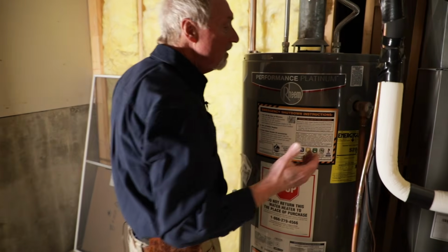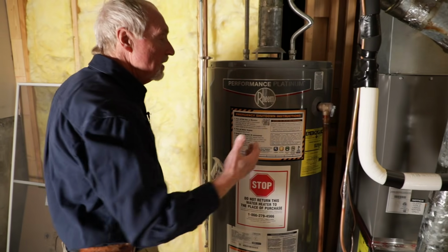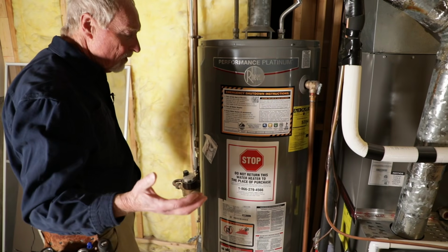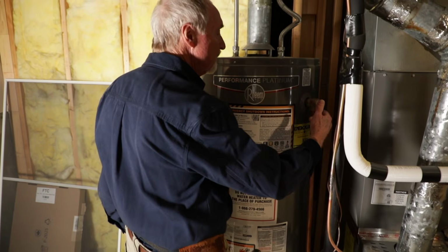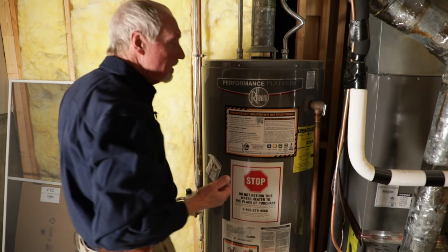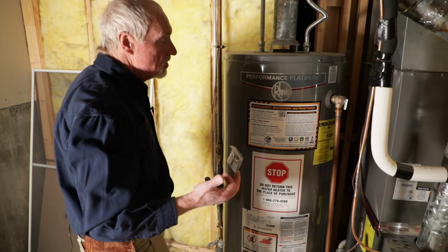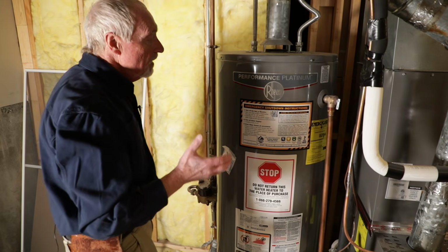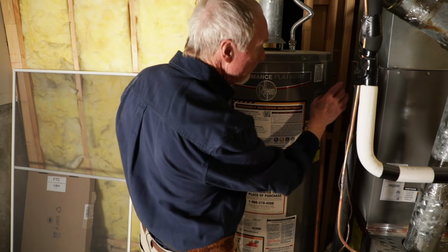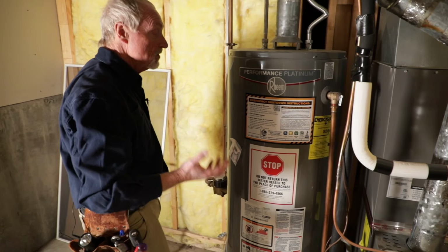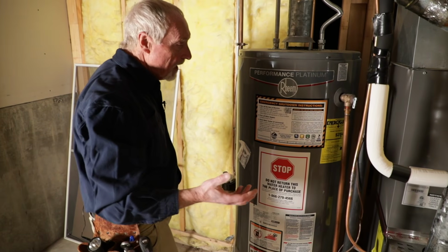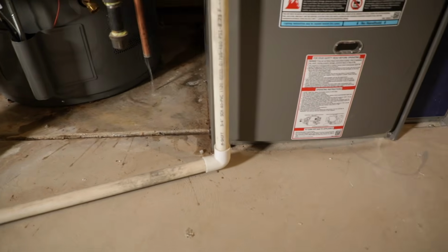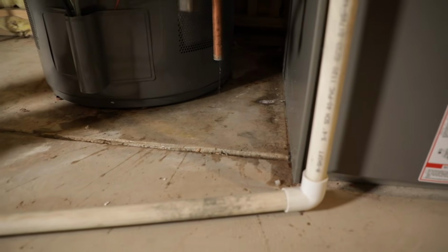On our TPR valve, you're not required to do anything with it. I like to check them when I think I can safely do it without causing any risk of an issue somewhere, but something you can simply do is spin the toggle on the handle here. If it spins like that, that's a good start, indication that our valve is loose and not stuck in any way. The instructions for this valve say it should be tested once a year. Most homeowners never do that. If you're comfortable doing it, you can test it by opening it up, getting a discharge of water, and making sure it stops.